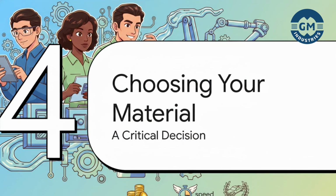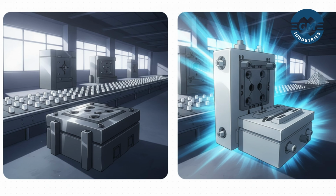Now, during that creation process, one of the most critical decisions you have to make is what the mold is actually made of. And this isn't some small detail. This choice is going to directly impact the cost, the speed, and frankly, the overall success of your entire production run. You've basically got two main contenders, steel or aluminum. Think of steel as the marathon runner. It's incredibly durable, it can last for millions and millions of shots, but it's a bigger investment up front. Aluminum, on the other hand, is the sprinter. It's cheaper and way faster to make, but it's going to wear out a whole lot sooner.